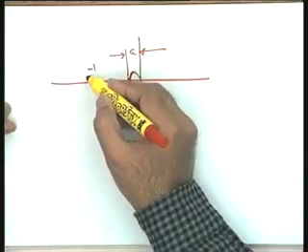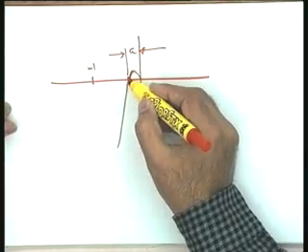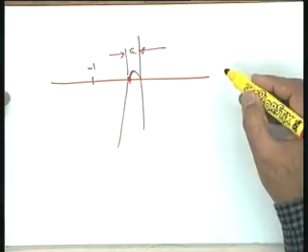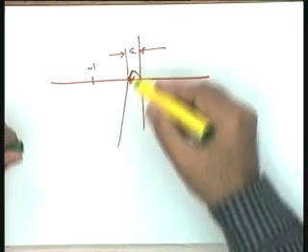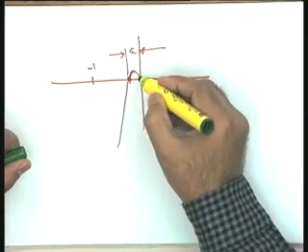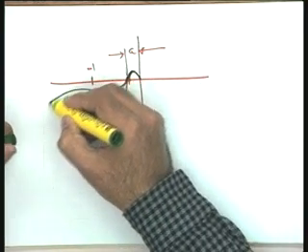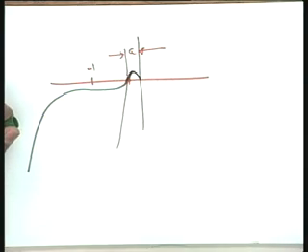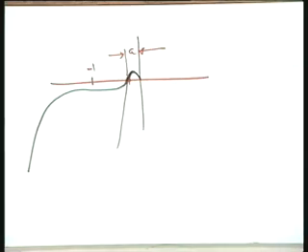So, naturally we are far away from the minus 1 plus j 0 point if this intersection magnitude is small. But you see the situation, after all this is a vector, it is not only a magnitude, it depends upon the phase angle as well. Let me take this intersection, but let me assume that the plot is like this. After all, this is also a possibility. This is also a polar plot of a typical system.